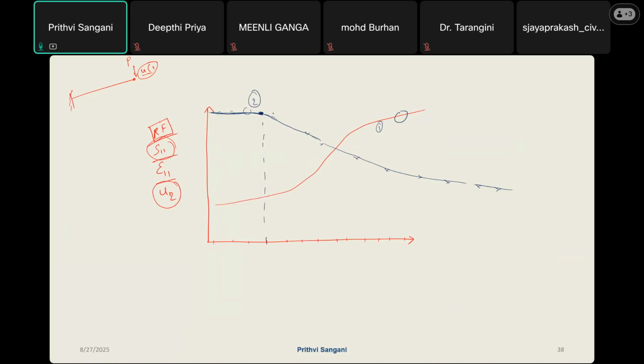So that's why I'll choose this optimized point as my mesh size for my actual analysis. Even in this red plot, which is case 1, at maybe this point the values are converging, and after this the values are almost the same. So I'll say that this mesh size is my converged point, and I'll choose this as my analysis mesh size.